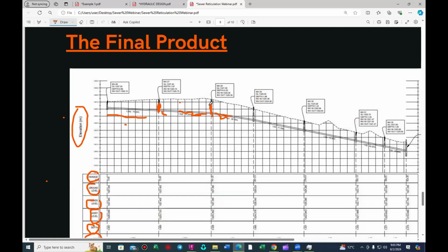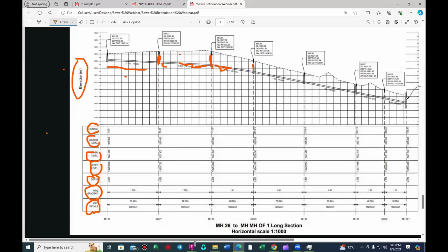It will start to rise in the manholes like that. And then when the peak factors subside, the sewer will start to decrease and flow nicely. So that's also another way we need to provide for manholes, because they also act as your temporary storage.